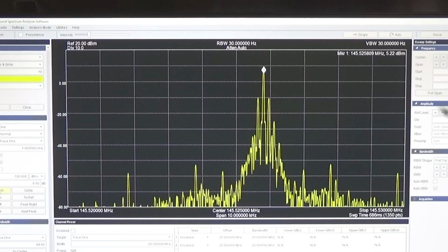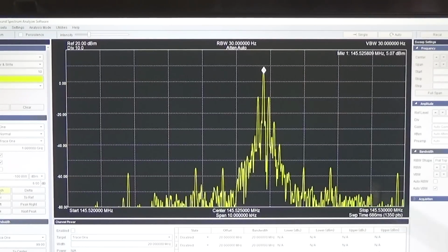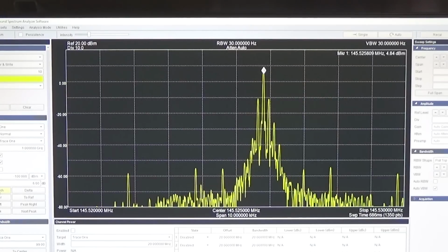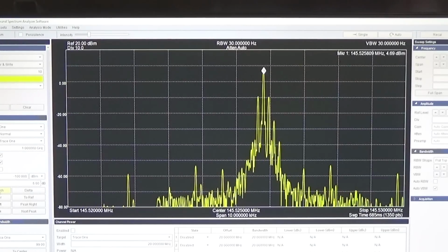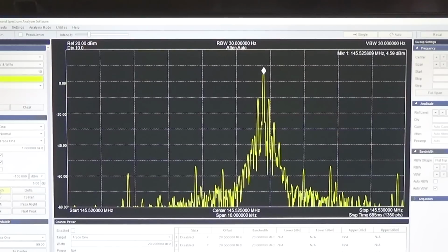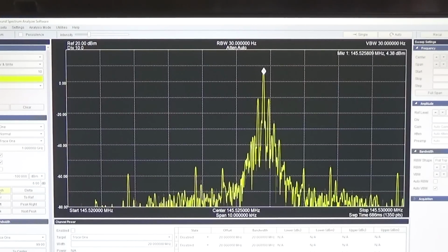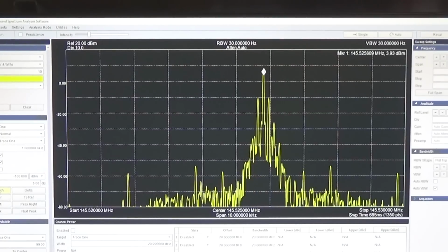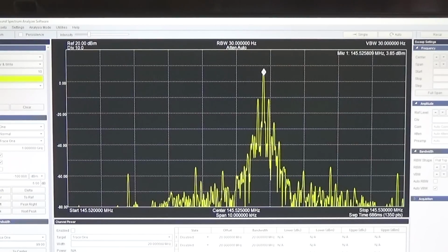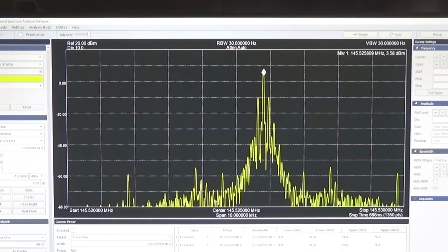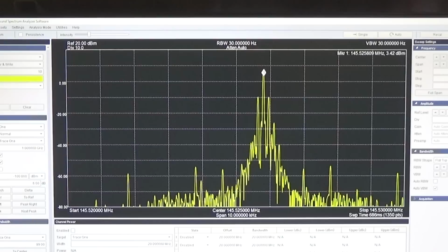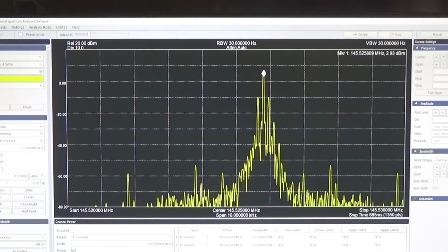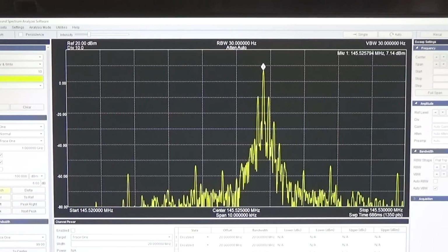What we can see as well here, 5 dBm, and when I started transmitting it was approximately 6 dBm, which is 6 or 7 dBm, which is equal to 5 milliwatt. What we have seen at first when we checked it on our radio communication service monitor. So that all is nice.